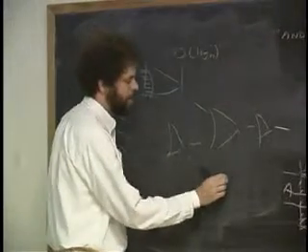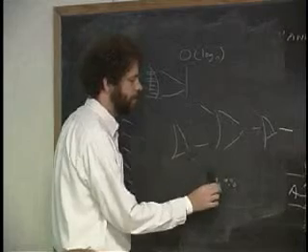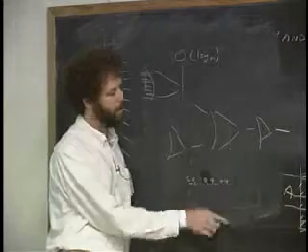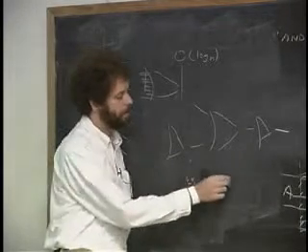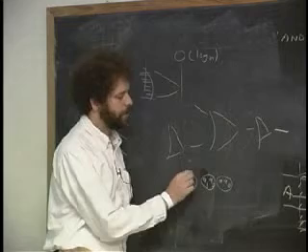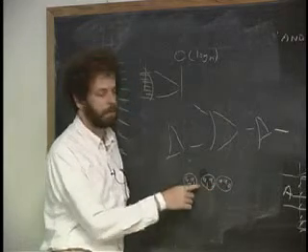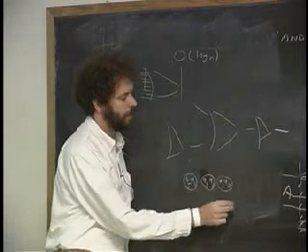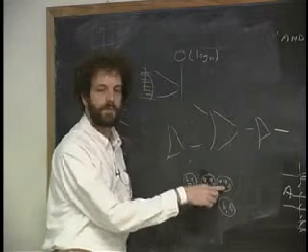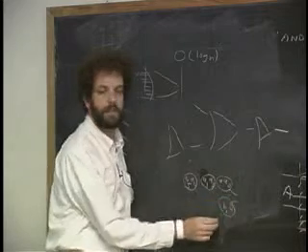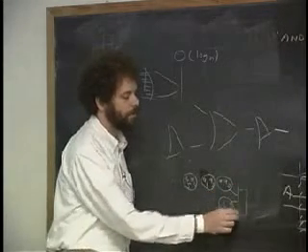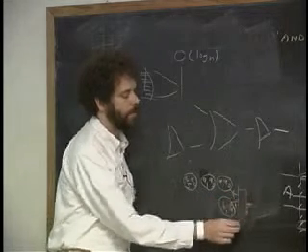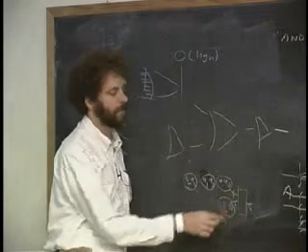So here's a sub 0, a sub 1, a sub 2, a sub 3, a sub 4, a sub 5. Rather than treating each one of these bits the way we've been doing now, treat them as little groups. So here's a number between 0 and 3. Here's a number between 0 and 3. And instead of adding bit a sub 0 with bit b sub 0 and b sub 1, we're going to add the number between 0 and 3 to another number between 0 and 3. Worst case, we'll put it into a lookup table. There's 2 bits here, there's 2 bits here. We can do this pretty fast, and we can get two bits out here that's a little bit faster.